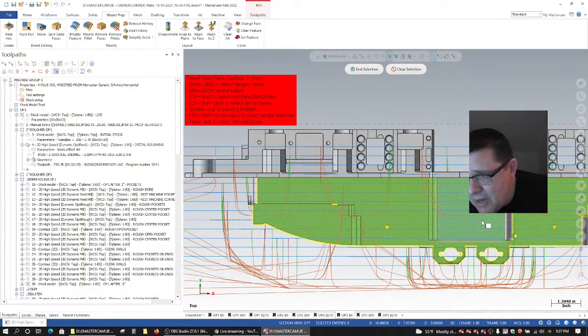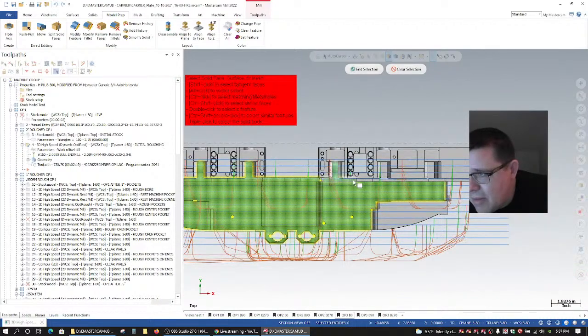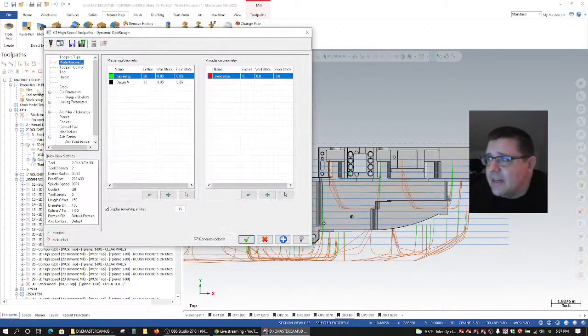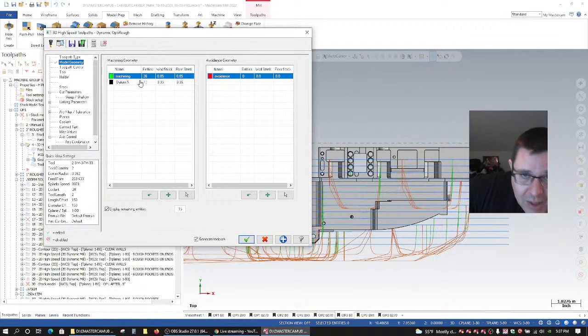I'm not going to make you all sit through reselecting all these faces. Okay, but let me just select a few of them. So select a few faces. You might end up with 100 faces selected here, but that is going to calculate a lot faster with 100 faces and a boundary and some depth limits versus having 4,000 or 3,900 faces because we selected the whole model.